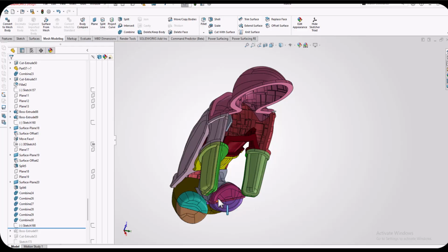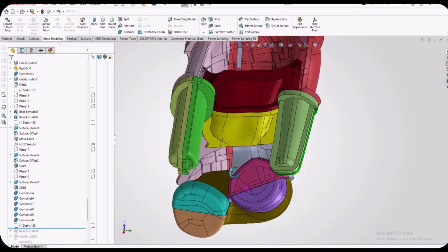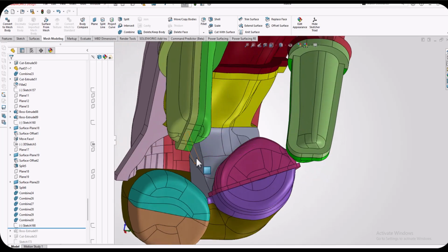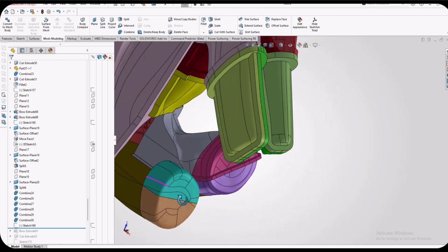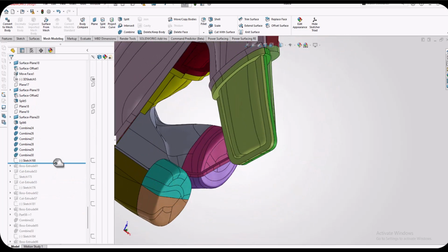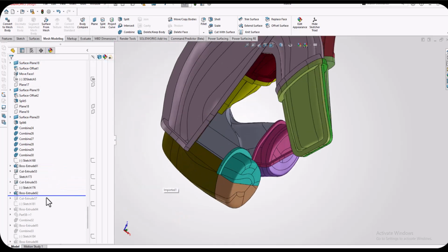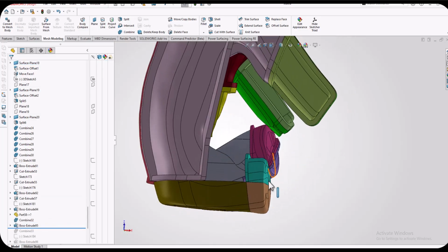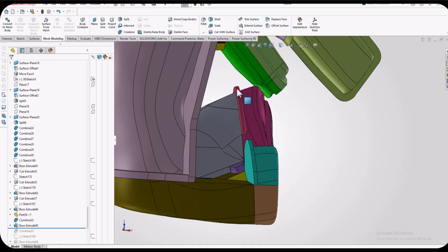As you can see, at this stage I created the connection flanges around each mold section and completed the assembly interfaces. During the design process, I realized that some additional parting lines would make the mold much easier to remove after casting. For example, in my original design, I hadn't planned to separate the mold around the knee area. However, as the project progressed, it became clear that adding a new separation line there would significantly simplify demolding.